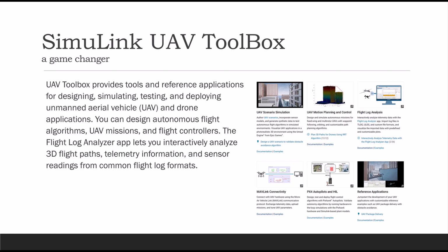We used S-functions and custom functions to decode. That was a very great method in 2020, but now in 2023 all of those headaches and complexity are solved and are now behind the scenes. You are going to use the blocks of MavLink connectivity in Simulink UAV Toolbox and do all of it in a modern, more efficient and easier way.